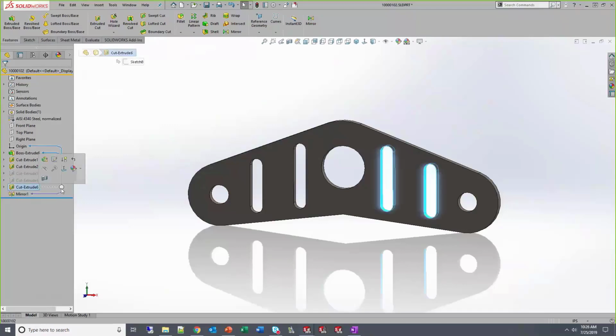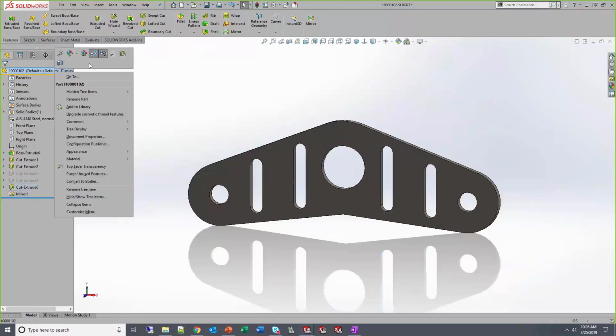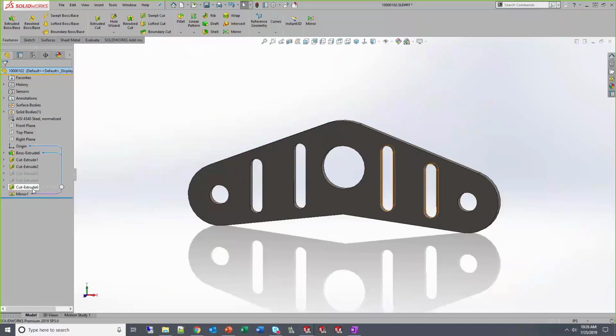Had a quick comment about the parent-child relationships. There we can see the parent arrows, the child arrows. You can get those by right-clicking at the top of the tree. It's called Dynamic Reference Visualization. I don't think they could have come up with a longer name for that, but there we've got the parents and the child arrows. So that's what we see popping up here right there.